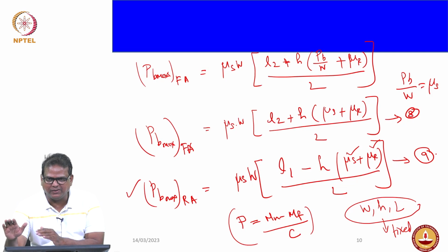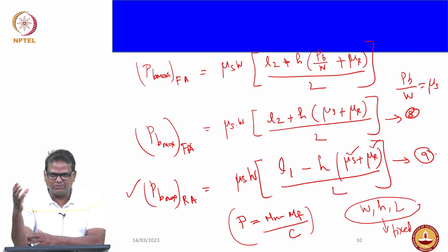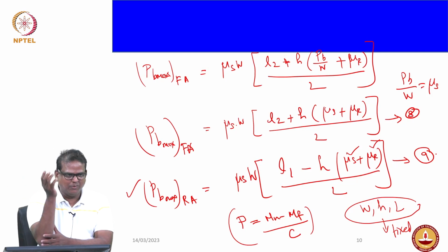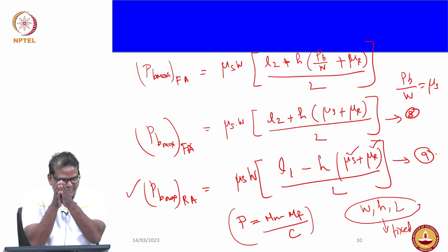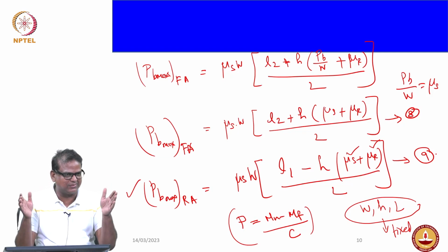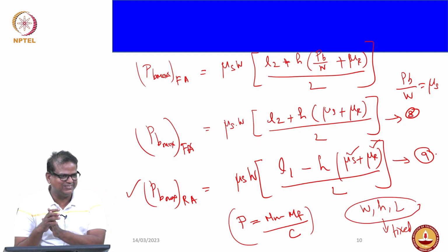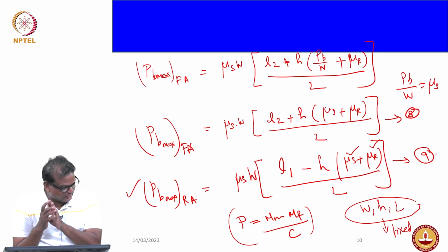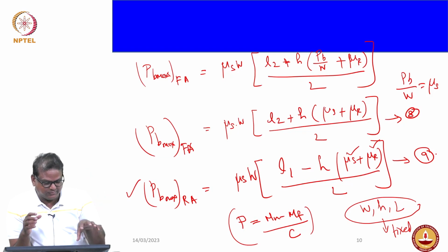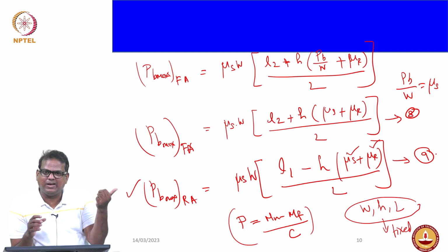When you apply the brake pedal, from the brake pedal fulcrum it will go to the vacuum booster, to the master cylinder. From the master cylinder it goes finally to the wheel cylinder. From the wheel cylinder, it will expand to activate things. That's what is happening. So in between, how do we optimize it? The distribution of braking force between the front and rear axle. Whatever you get, PB max front axle and rear axle must be the same during the pedaling effect also.